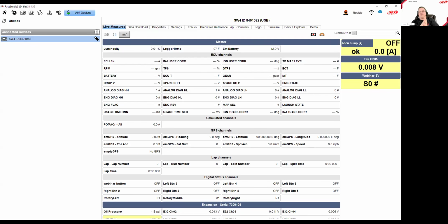Jeff mentions, do we need to worry about a fail-safe state if the EPM and dash lose contact with each other via CAN, I suppose, right? If the fail-safe state is to keep the status quo, essentially. Now, if you would like to program in a mechanic that deactivates channels, it's all built into the power outputs. So I can come into my power outputs and I can say if safe ignition is no longer, if I lose the ignition leg, the PDM is going to shut down.